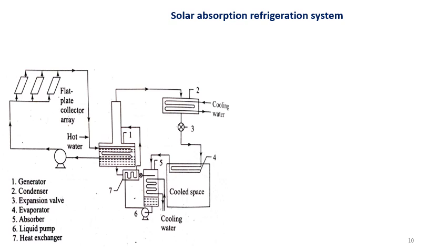The refrigerant vapor goes to the absorber, where it comes in contact with the solution, which is weak in refrigerant and which flows from the generator. Okay. So the vapor is absorbed in the solution, which is then returned to the generator. A heat exchanger is used for sensible heat recovery and greatly improves cooler COP.